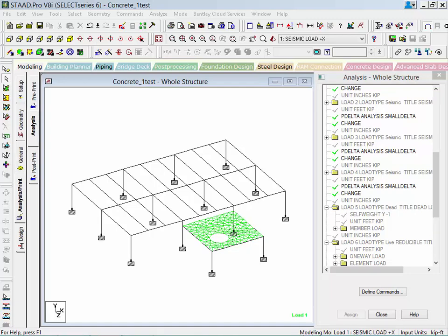Now, since this particular model contains a multiple analysis command structure, and since it also includes repeat load combinations as primary load cases, we must also use an additional command called the SET NL command. This will be required to allow STAAD.Pro to set aside some additional memory space for information to be added later. It's typically needed when you have a multiple analysis run and then additional load cases are added after an analysis has been performed.